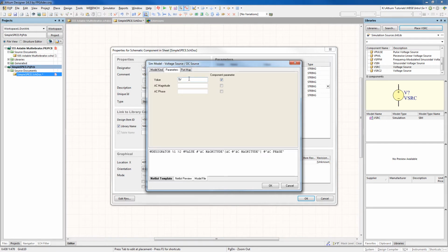Altium is smart enough to know that if you put like 5 volts or 5 amps, it's smart enough to know to remove that part. So you can leave this like this so that there's enough detail to it. The only danger here, just as a side note, is that if you're doing something like 2.5 volts, then it needs to show as 2.5 volts. There's a nomenclature that people use where it says, for example, 2V5, and that won't work.